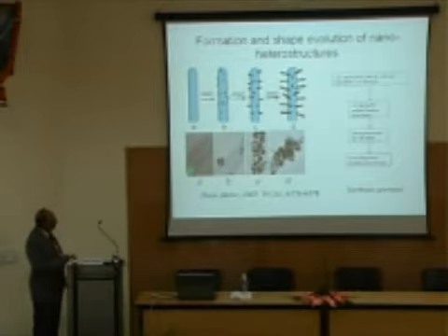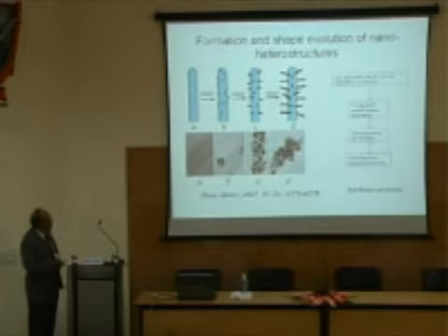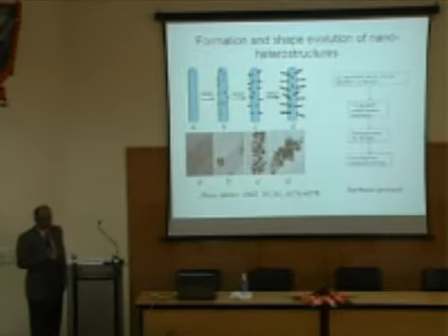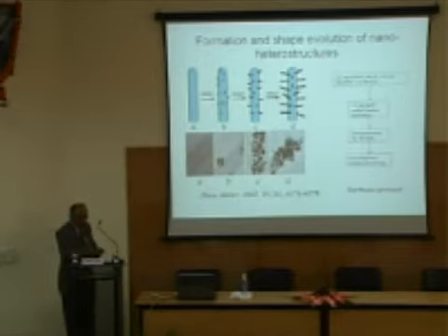So, this is a bare carbon nanotube, and as the reaction proceeds, small particles of platinum are deposited on the carbon nanotube, and with due course of time they will form oriented growth. So, this is the carbon nanotube, and on top of that you will see this assembly of platinum particles growing as rods. Okay? So, this is another way you can generate nanostructures which can be used for interconnects.